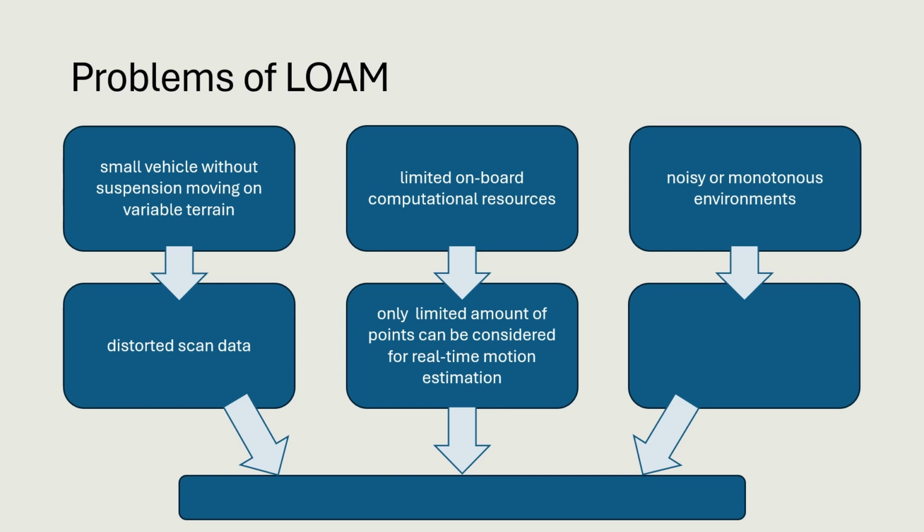The effect always can be seen when using objects which might change their position or orientation over time to extract features. Not only the consequences of environments with moving objects, but also of those with monotonous structures are problematic. If similar objects occur repeatedly next to each other, extracted edge and planar features could possibly be matched faulty. If no objects at all are available, for example in case of just a blank and even wall, we could potentially run into a situation where no helpful features are provided.